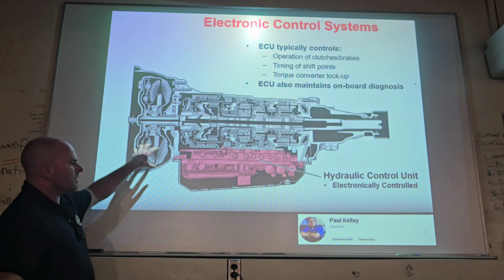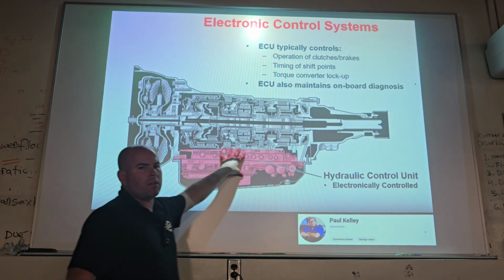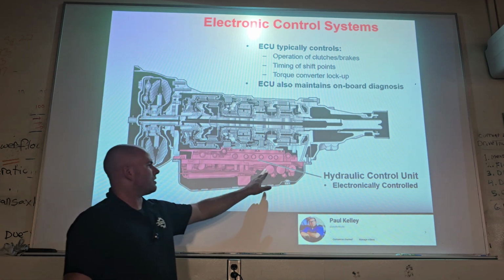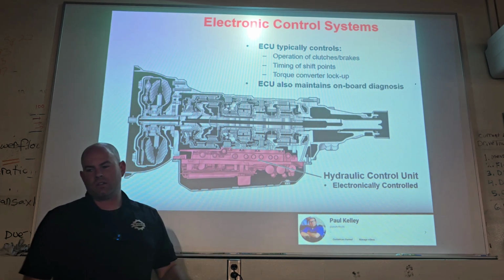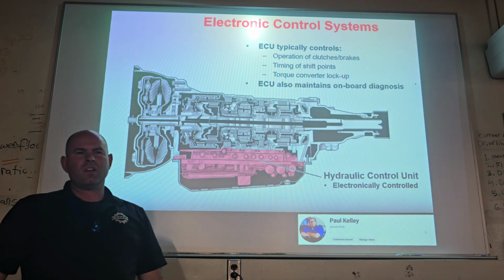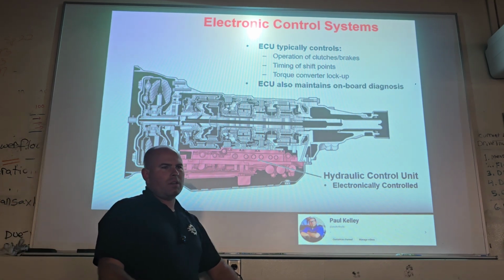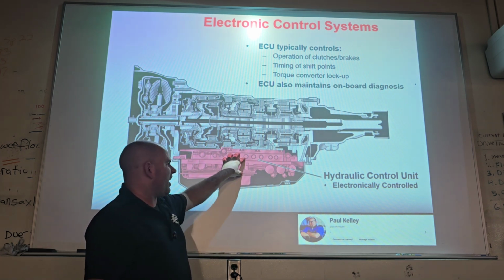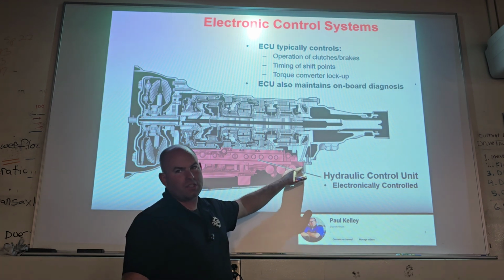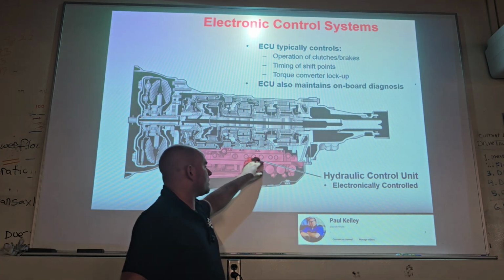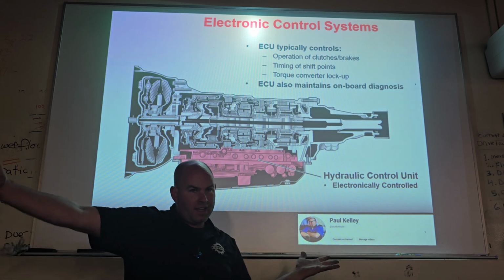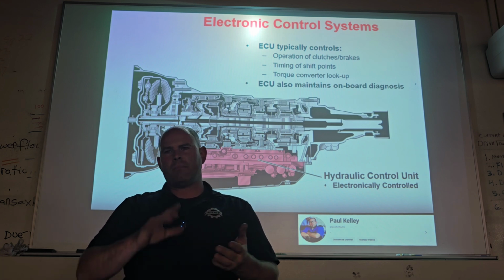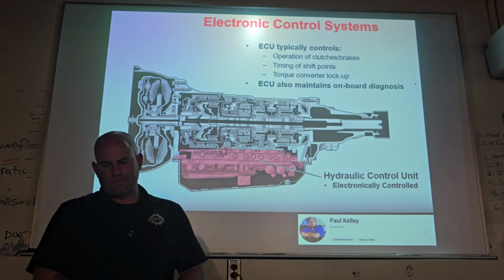Okay, coming up, that we're in here now. We're in the hydraulic control unit like we were. So basically, I'm talking valve body. But on this one, you'll notice, see these right here? You know what those are? Shift solenoids, yeah. So shift solenoids do the work. Before, the valves did the work, but the valves were controlled by hydraulics. Now the valves do the work, but the valves are controlled by the shift solenoids. Make sense? What are the shift solenoids controlled by? ECU. Yeah, some sort of ECU. It could be the TCM, could be the ECM, could be a PCM, but it's going to be computer controlled one way or another. Cool.